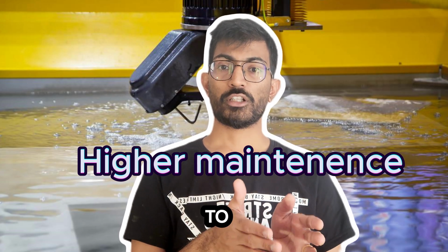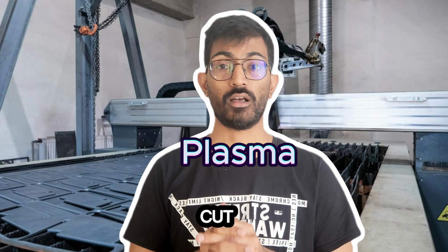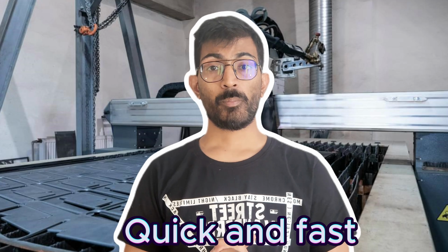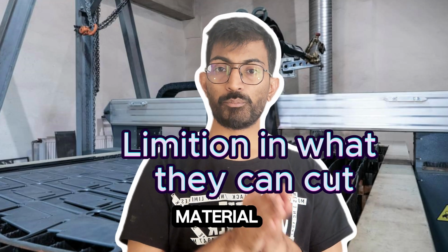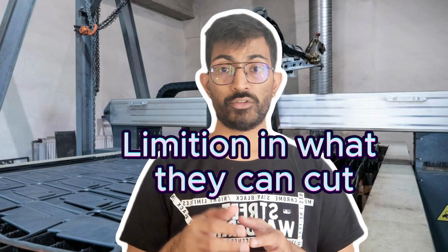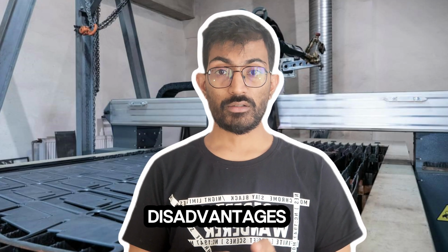Now let's move on to the third method, which is plasma. Plasma and oxy-arc cutting are really good, really fast, and they can cut a really thick metal on their bed. So this is a really good advantage. And the good thing about plasma machines is they are really cheap. The disadvantage of these machines is they can only cut a certain type of material. For example, plasma arc can cut stainless steel, but the problem you will face is that stainless steel cut on the plasma arc will have issues with rusting in the future. So ideally, no one would prefer to cut stainless steel in plasma cutters. These are the main advantages and disadvantages of plasma cutting.